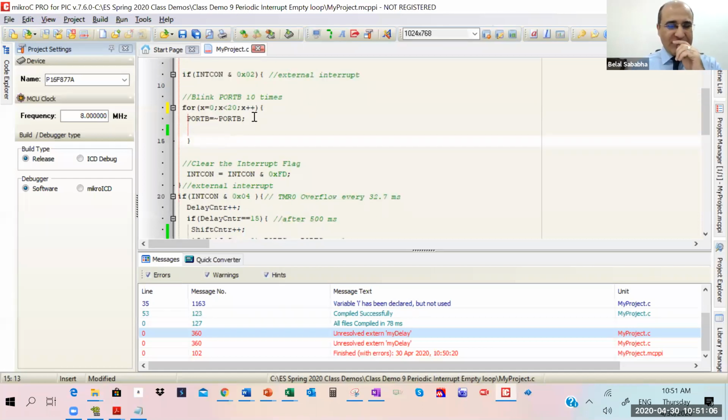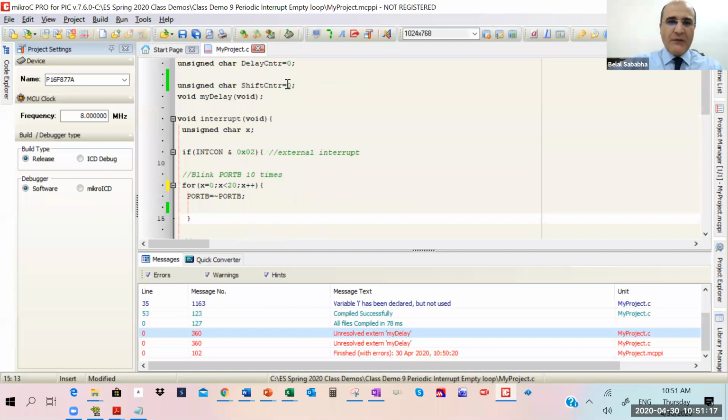Well, easy. We can just do this: whenever an external interrupt happens, we set something. Let's call it maybe blink timer, or external interrupt counter, whatever. It needs to count to 20, so an unsigned character would do it. Let's call it blink counter, and initially it is 0.